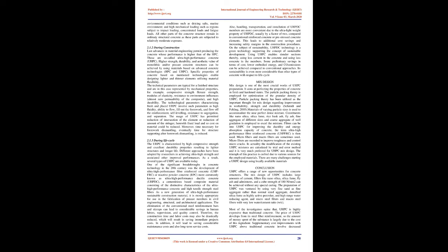Emmons 1993. Rehabilitation and strengthening of deteriorated concrete structures is a heavy burden from the socio-economic viewpoint since it also leads to significant user costs during this rehabilitation works. UHPC can be used to stiffen and strengthen the zones where the concrete structures are exposed to severe environmental conditions such as de-icing salts, marine environment, and high mechanical loading such as regions subject to impact loading, concentrated loads and fatigue loads. All other parts of the concrete structure remain in ordinary structural concrete as these parts are subjected to relatively moderate exposure.